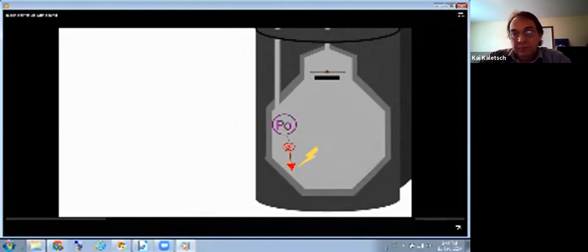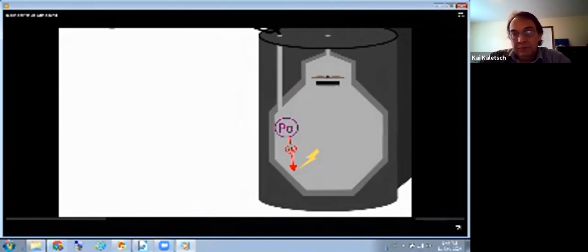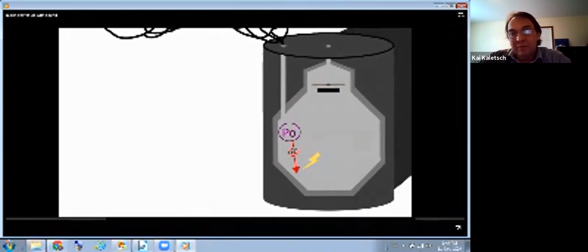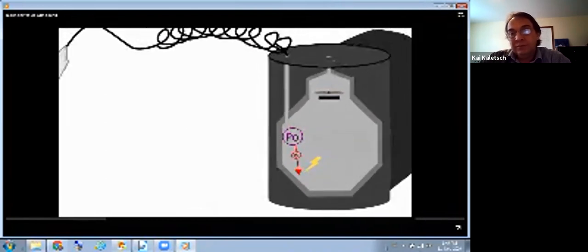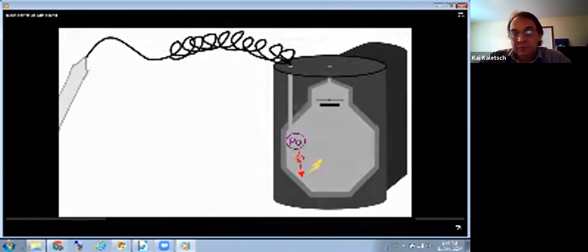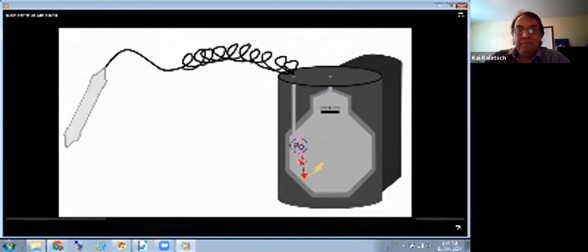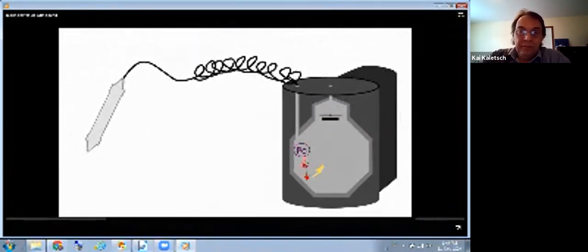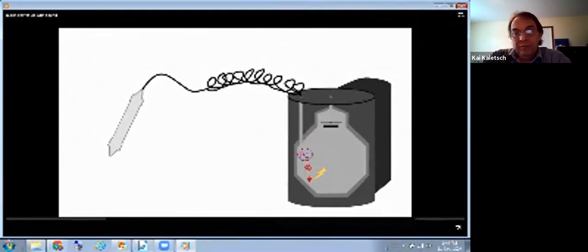This background process is not perfect. If you expose the sniffer to hundreds of picocuries per liter, you will not be able to measure air with 10 picocuries per liter accurately. So, always do your ambient air measurements before you do your sub-slab measurements.